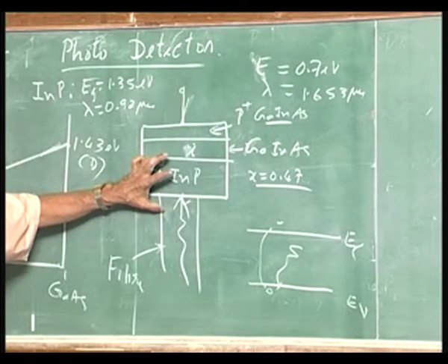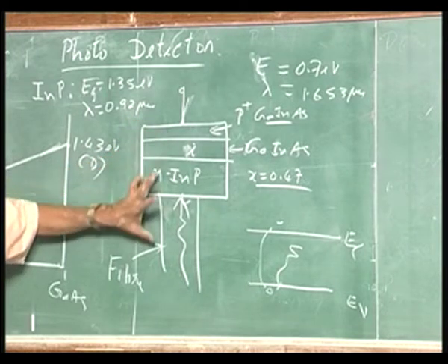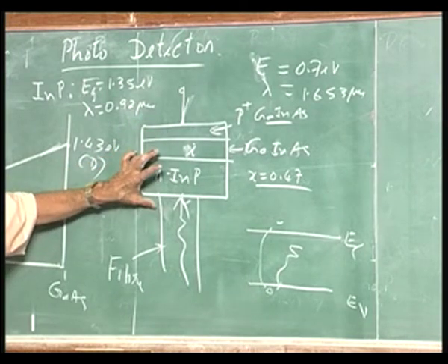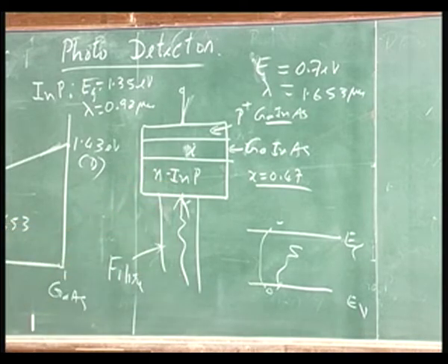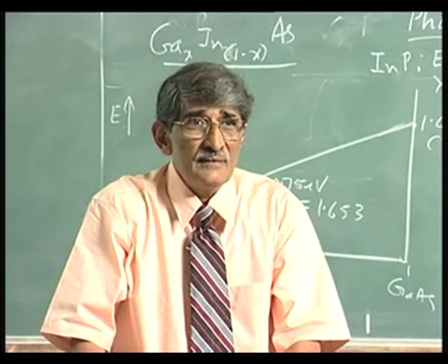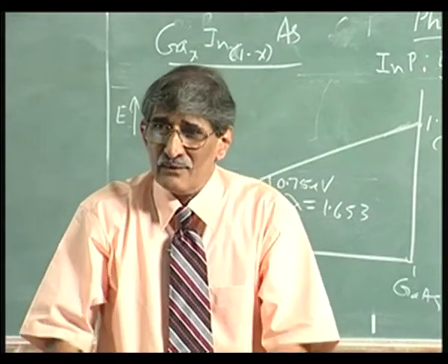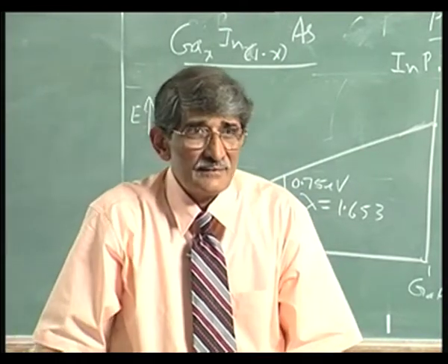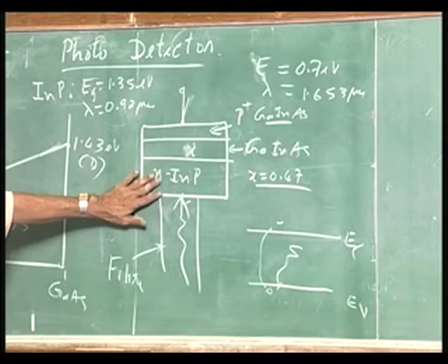And this is a thick layer. This is very thin, 0.2 microns or 1 micron. So, if this is 100 microns or 200 microns, whatever light is falling here is absorbed here. It is just absorbed in the bulk. Electron-hole pairs are there in the bulk. What happens if you generate electron-hole pairs? They just recombine, fall back, no effect. Okay, that is all. It is converted into heat, then it recombines. So, there is nothing happening there.